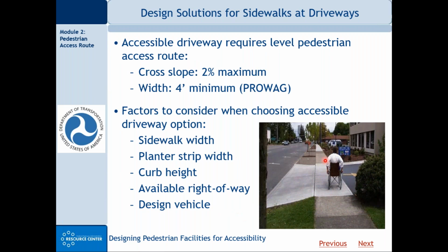We could make a compliant sidewalk that vehicles that need to access that business or land use could not make it, could not be able to access it. And that's not what ADA wants. We don't want to affect the livelihood of businesses, put them out of business because people can't access the land use. So we have to balance accessibility to the land use with the ADA requirements.